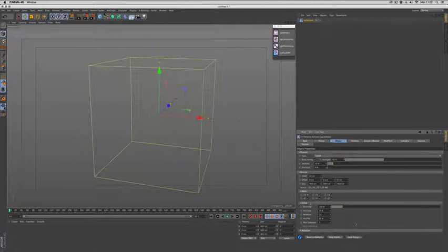The solver gives you options for retiming, such as slowing it down or speeding it up, accuracy of the solve, and how many iterations. The pick flip option gives you control over changing the blend between a pick solver and a flip solver. Each do different things. Maximum substeps are the substeps within the calculations. Adaptive is for the bounds.